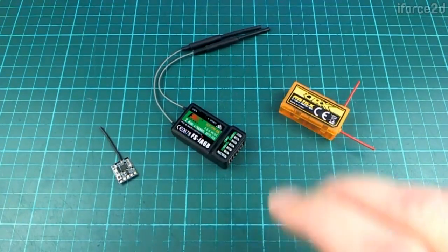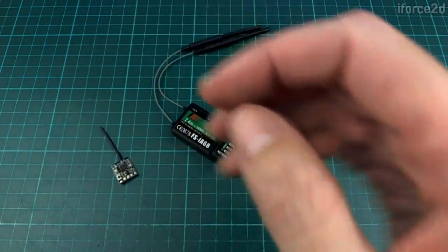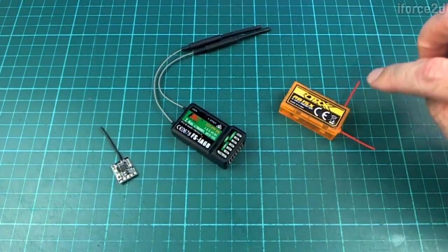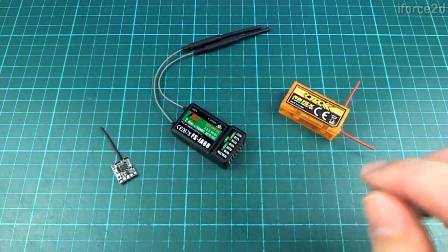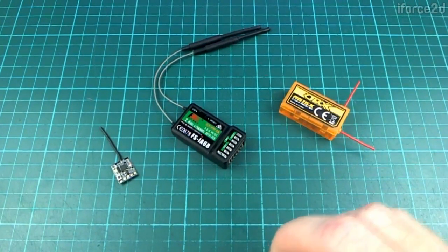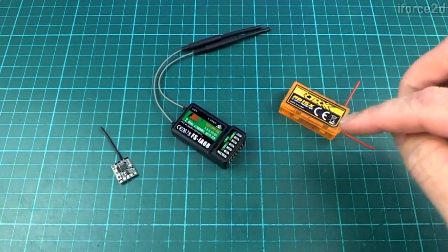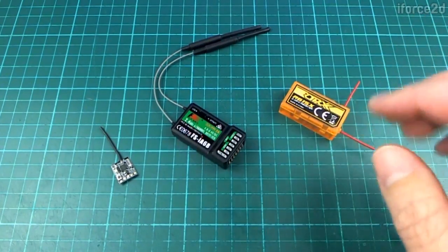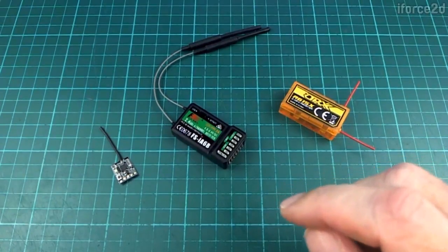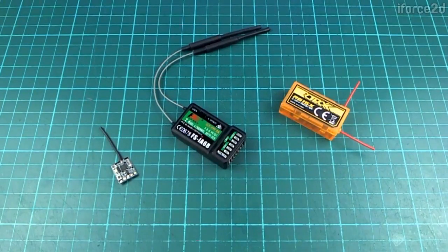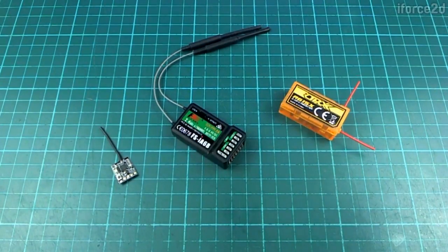This diversity can be quite useful on something like a plane or a quadcopter that rotates and turns around as it flies, because sometimes the orientation of one antenna may be in a good position to pick up the signal, but the other one is not. In that case, diversity is a very handy thing to have, and you can see that this one's set up so that these are at 90 degrees. It turns out that having them at 90 degrees to each other like that is the best way to ensure that whichever way your plane or your quadcopter is facing, you're most likely to get a decent signal. And speaking of signal, the frequency range that these receivers operate in is most commonly the 2.4 gigahertz